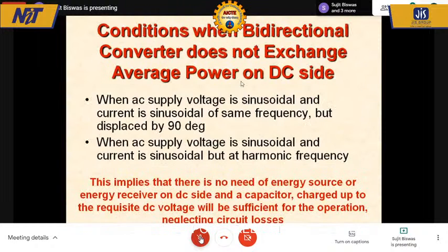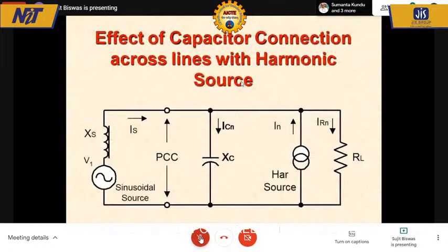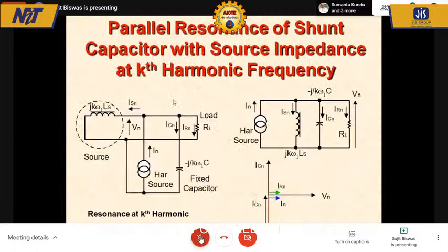So if you have an inductor, let's go back to that network. Yes, if you have an additional inductor put in here on the source side, the total inductance here will be detuned from the specific capacitor, because remember, I had assumed that the value of LS was tuned in parallel to the given value of C. If you change the value of either LS or C, you will be able to detune them. So if you add an inductor here, it is no more going to remain in resonance.